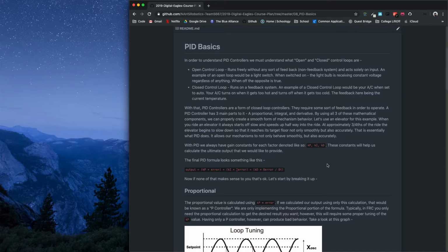So what I ended up having to do was account for that by setting the encoder counts to be lower. So I would be stopping earlier, and then gravity would be stopping it at the level that I would want it to be at. Now, obviously, this is very inaccurate and inefficient, mainly because as the strings get loose, it basically won't be in the same consistent environment every single time. And this sort of affects the PID controller to an extent as well. But this makes the initial solution incredibly inaccurate, very inconsistent. And so I ended up implementing the PID controllers later on, and it definitely made the entire system much more accurate.